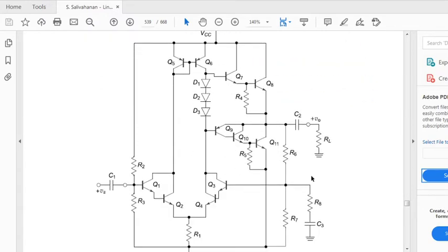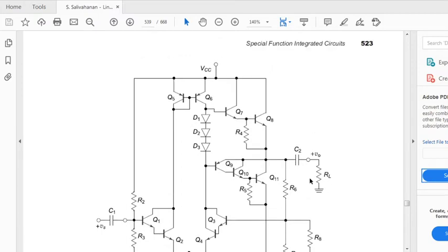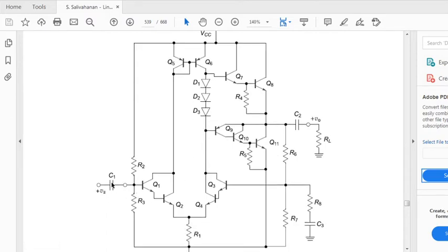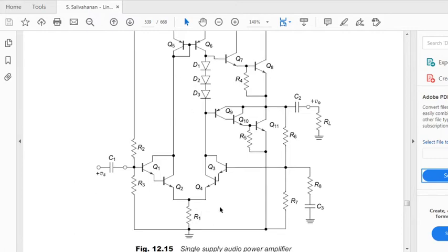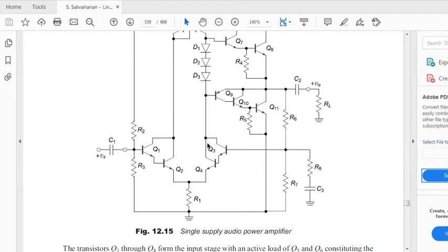So if you have seen, again you are having the Darlington pair connection, which is offered by your Q7, Q8, Q9, Q10 and the Q11, and you are having the three diodes, no? So between your two complementary outputs, NPN and the PNP configuration, these three diodes are there. That is the one that drives your complementary pair. And a current source will be there, which in turn is realized with the help of your transistors, and an input stage is also given as a differential pair with active loads. Okay, so that's what it is in the case of your audio power amplifier.